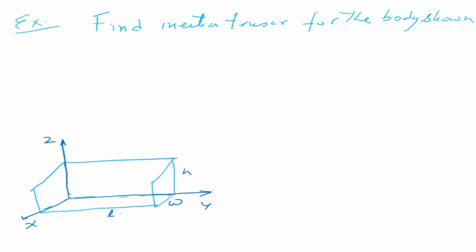Now, what we are trying to do is find out the mass distribution, or the inertia tensor, of this body, so that if you are going to rotate about a particular axis, maybe I want to rotate about the x-axis or the z-axis, how much energy is required. So we simply put it into the formula and get those 9 elements. So let us just do one example of one term, and the rest of the terms you can do easily.